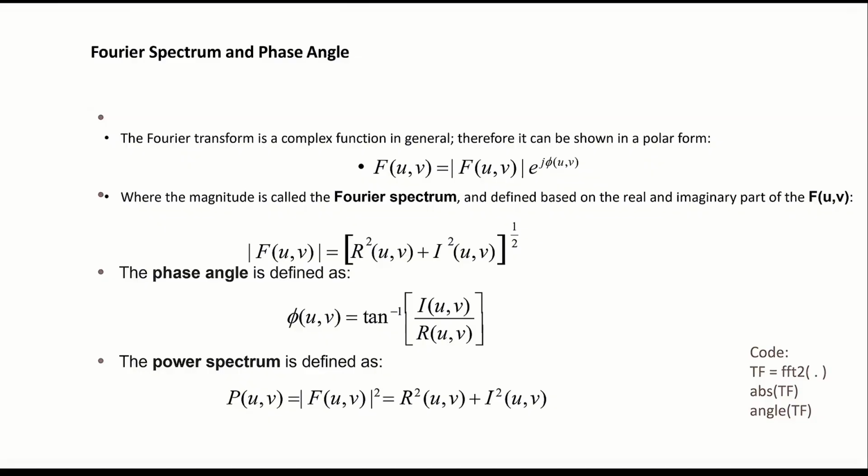If you take a Fourier transform, it's a complex number, right? So if it is a complex number, it has a magnitude and phase. Okay, so we have to see what is the magnitude. Magnitude is the square root of the real square plus the imaginary square. And angle is the tangent inverse of the imaginary by real. Just simple. However, for the images, I need to see what information is in the magnitude and what information is in the phase.